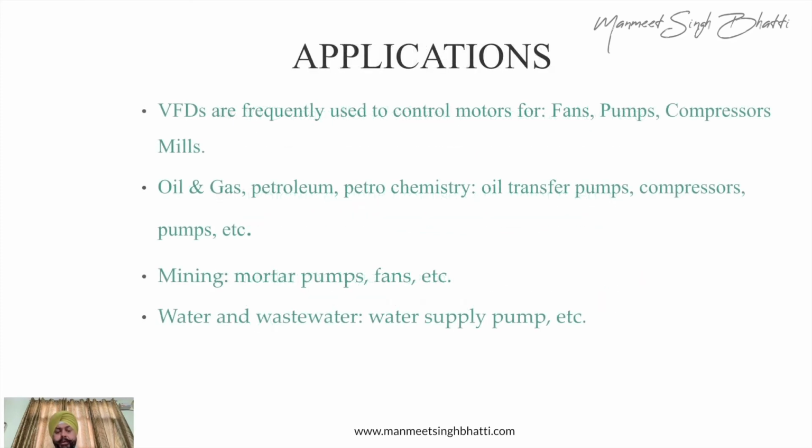Now, coming to the applications where we can install it, as I've explained earlier also, VFDs can mostly be installed on fans, pumps, compressors, any kind of crushing mills, wherever you want. Basically, any motor, any rotating machinery where you are using an electrical motor, you can put in a VFD.